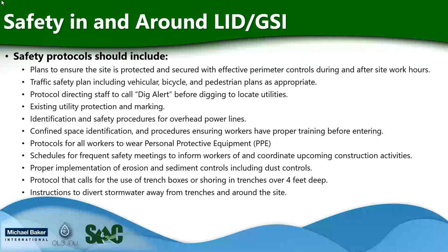There should be confined space identification, protocols for all workers to wear the PPE, schedules for frequent safety meetings to inform workers and coordinate upcoming construction activities, proper implementation of erosion and sediment controls and dust controls, and protocols that call for the use of trench boxes or shoring for trenches over 4 feet deep. And then instructions to divert stormwater away from trenches around the site.